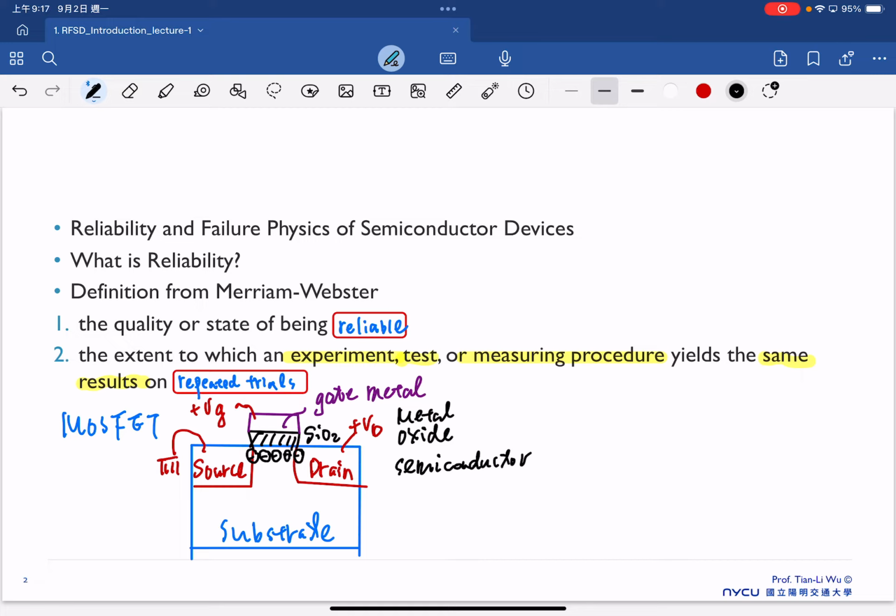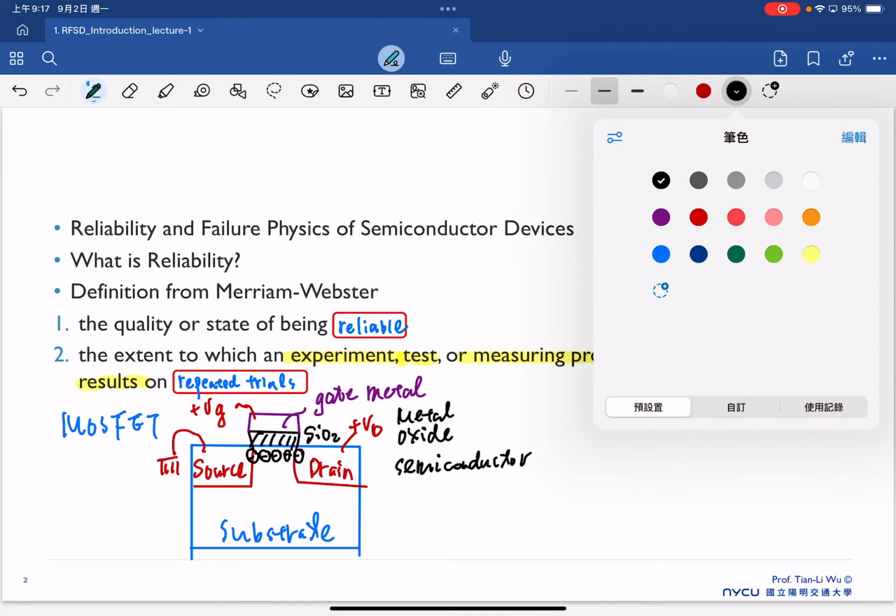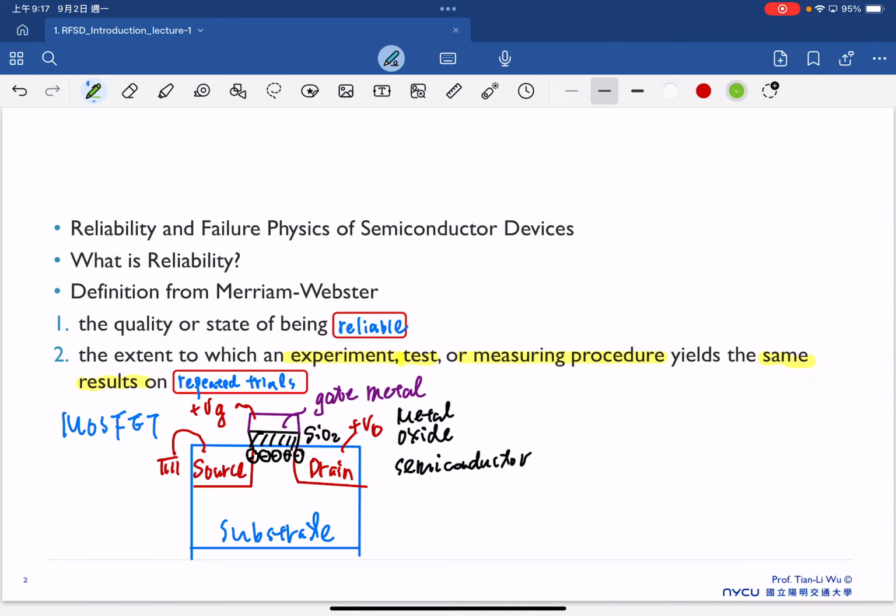The gate dielectric, silicon dioxide, is an insulator, so we expect that the gate voltage applied here can induce negative electrons here. That's pretty much high school physics: you apply gate bias from one side, for sure you'll start to attract electrons. And in the meantime, because we also apply the drain bias on the right-hand side, we can expect these negative electrons to flow from source to drain.